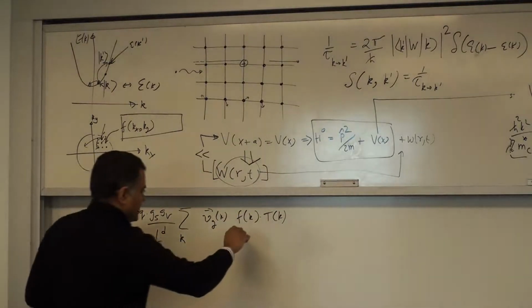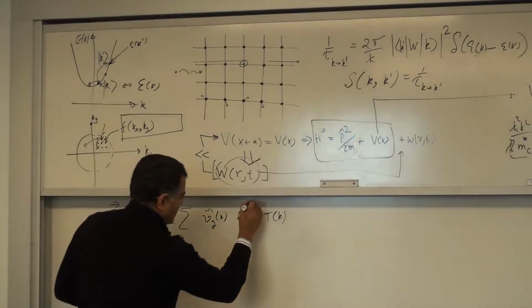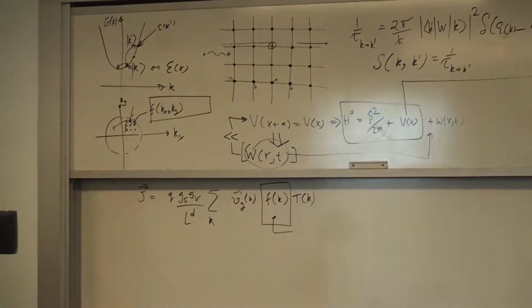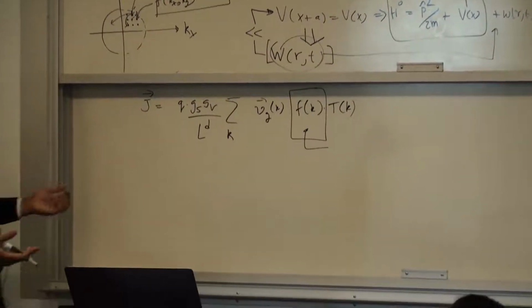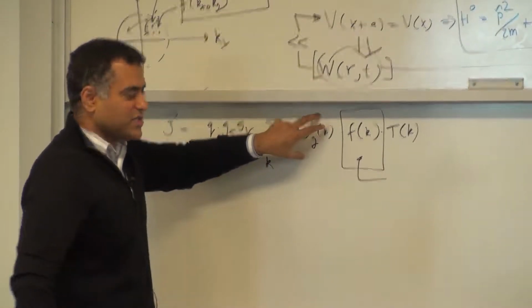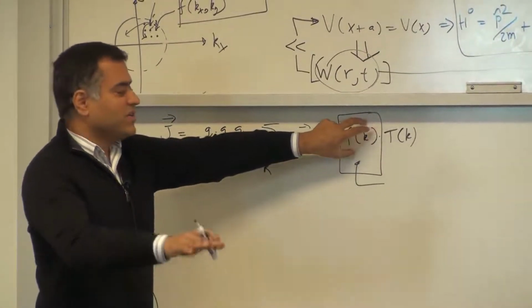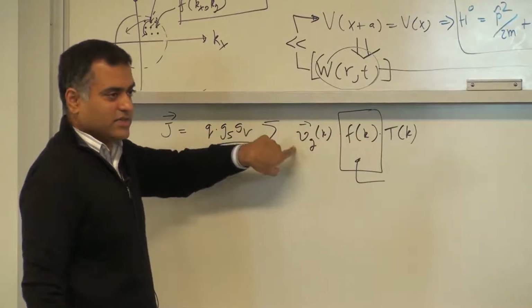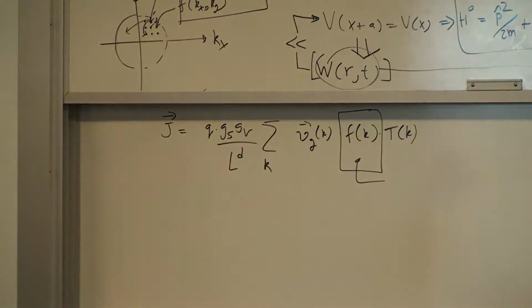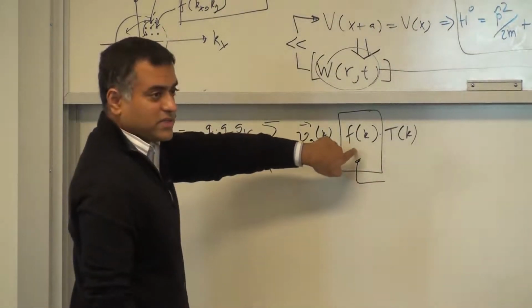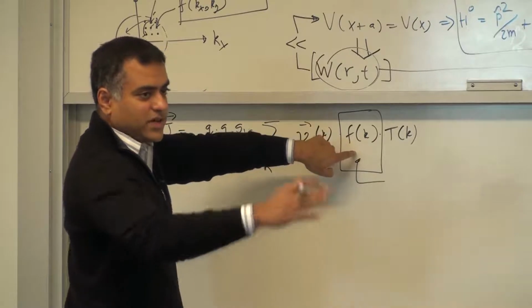So this is your full-blown current expression. I'd also emphasize in the beginning that a lot of transport, we're bothering about this most of the time, because the hard work of knowing the band structure is done. The band structure information is here, but this is how you are controlling with the source, drain, defects, all of them enter here, not here. So transistor switching on off that we just talked about, all of that is from here, right? So the Fermi functions are changing, right?